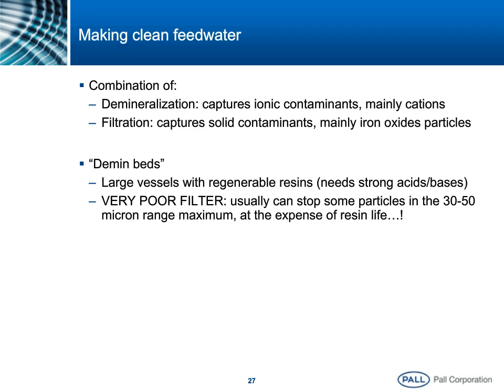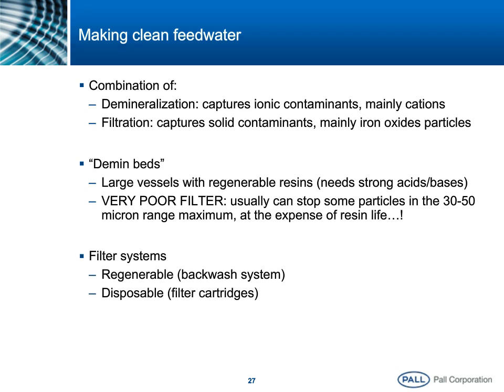In any case, it is a very poor filter. Usually you'll find 30 to 50 micron particles caught in the vessel itself. But think of it, this is at the expense of resin life. The fact that we find solids in a resin bed is not a good thing, because it should not be used as a filter. It's better to use a filter.